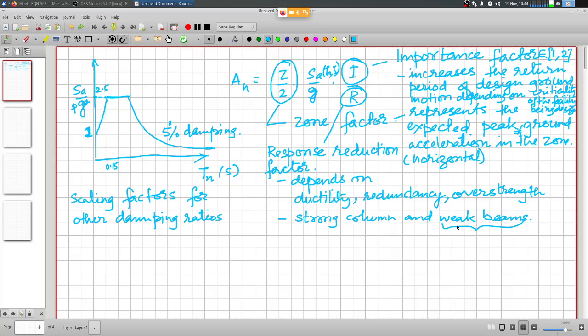So it is extremely important that during the construction your reinforcements should be tested for failure, and if the yield strength turns out to be much higher than what is assumed in the design calculation, either the design has to be revised, or the reinforcing steel batch has to be replaced.